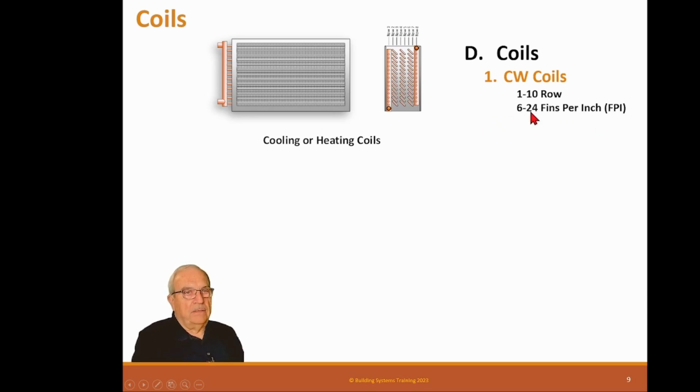Now, I don't know why the manufacturers do this. You should never use a 24 fin coil. And the reason is you can't clean it. So what happens when these get dirty, a technician has to come here and clean this coil. And the way he does that is he sprays water and foam on this. And this foam is designed to expand its way through the coil and push the dirt out the other side. And then he takes a hose and he sprays water, not a pressure washer because that damages the fins, just a regular hose, and blows water through there to get it clean.